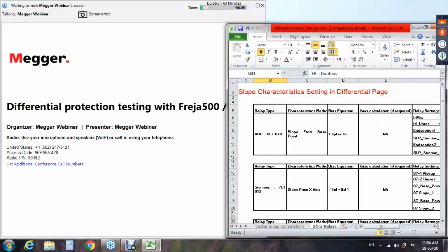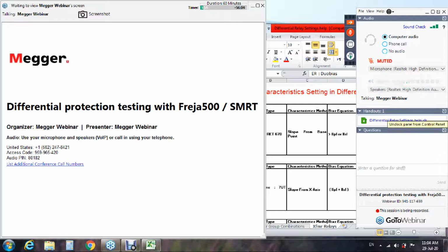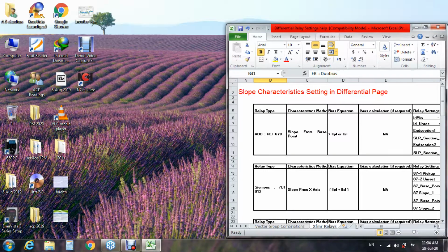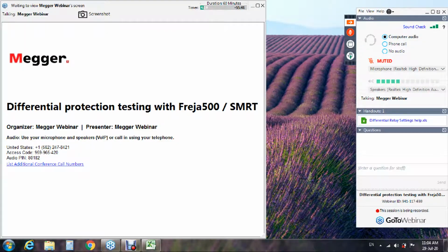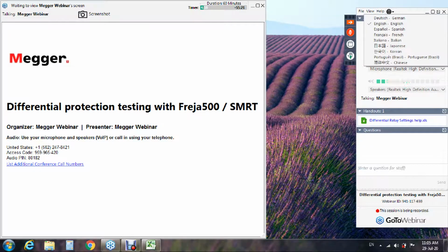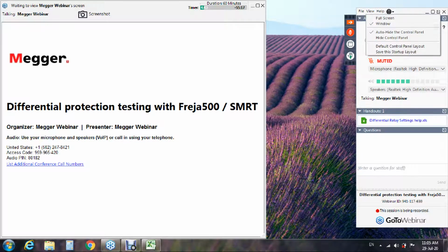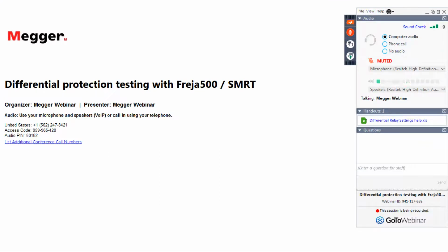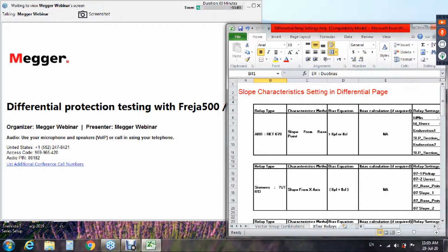Differential protection can be applied in different assets like transformers, transmission lines and cables, generators, motors, bus bars. And the idea of it is similar to what's stated in the graph to the left here. When I have a protected object, it doesn't matter what the protected object is, a line, transformer, generator, and I have sides of currents going to this protected object. The summation of these sides under normal condition should be equal to a value near 0. The summation of these currents going to this protected object, we call the differential current, where we use it as a criterion to state whether our protected object is in healthy condition or in non-healthy condition, like a faulty condition, or it has an abnormal condition.